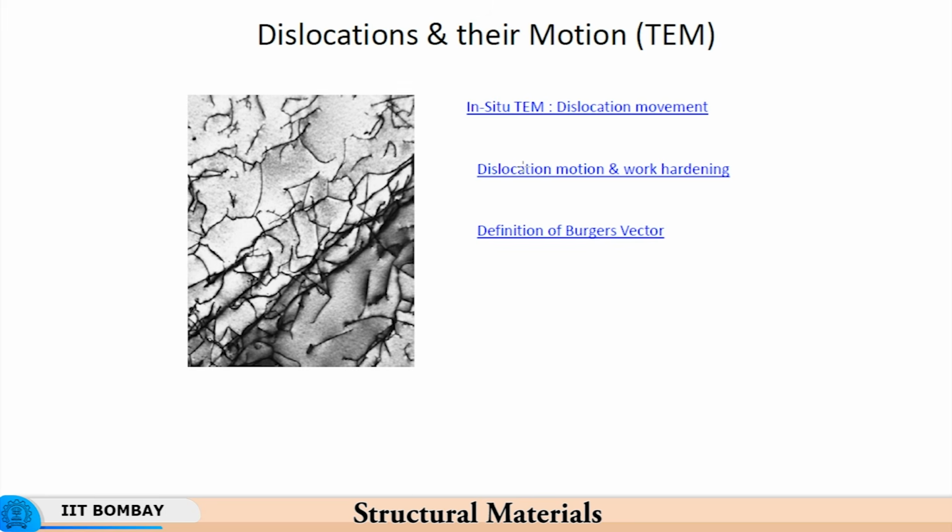They have sufficient magnification to reveal the dislocation structure inside the material. An in situ TEM is something that enables you to do a tensile test or cause some deformation as the transmission electron microscope is watching the movements of dislocations. So basically it captures the dislocation activity live.